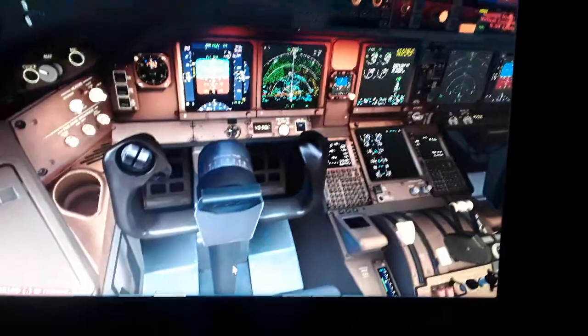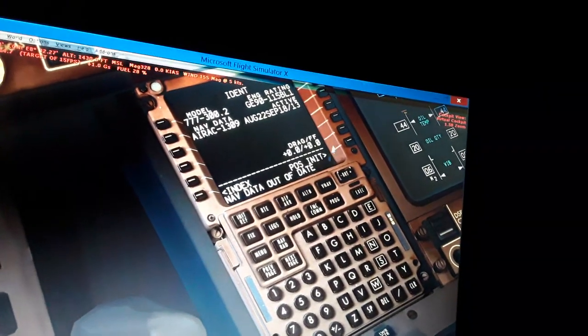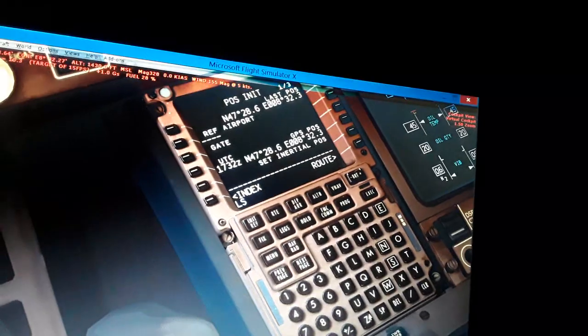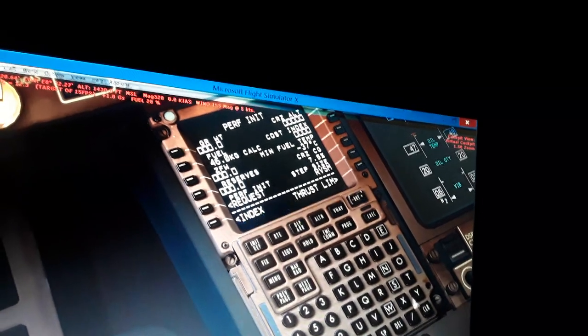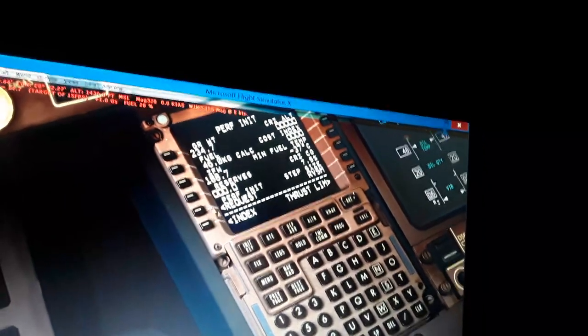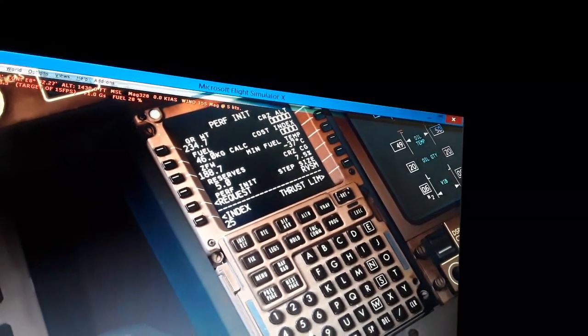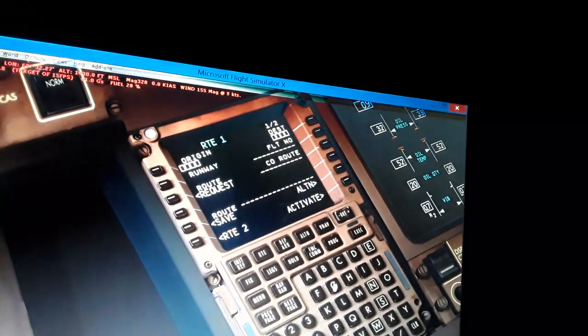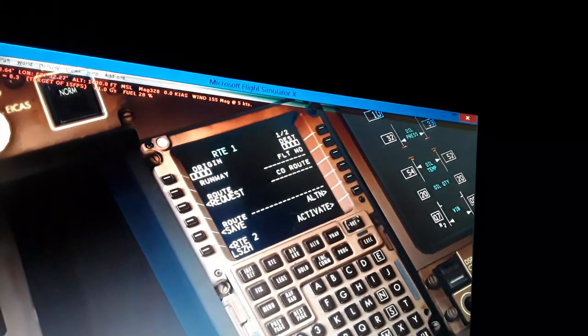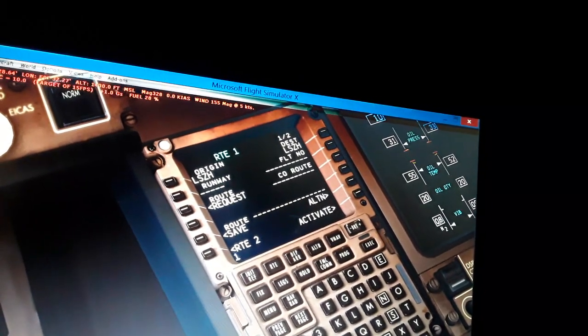Now we need to make one last step. The electric is back. So we have the FMC here, the menu, the flight management computer, position, initialize, LSZH, the reference airport, zero fuel weight over here, gross weight, reserves, cruising altitude 35,300 feet here, and the cost index 100%, minimum fuel temperature, the route from this airport at LSZH back to this runway 14.